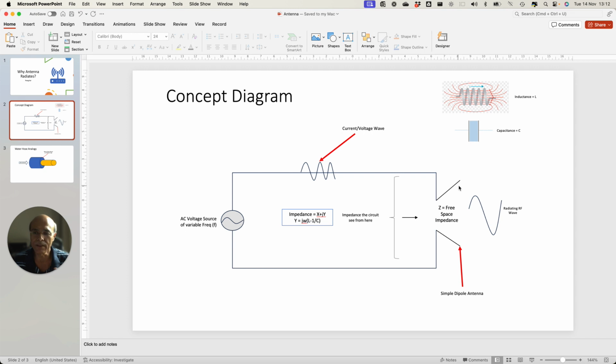The antenna could be of various types. I'm basically taking a dipole antenna here. The length of the antenna is very crucial. That is why, when you are operating in a lower frequency band, let's say 700, 600, 500, the lambda size increases, and the antenna size also increases. It becomes very difficult to incorporate that antenna within the mobile phone. So it becomes extremely challenging for us to deploy an antenna at lower frequency in a mobile phone.